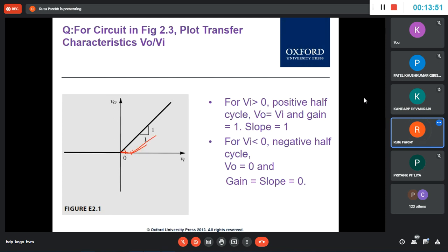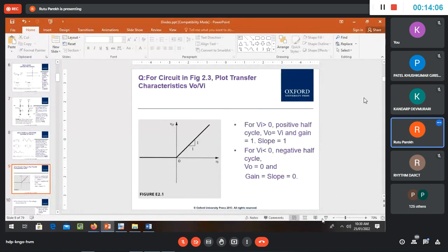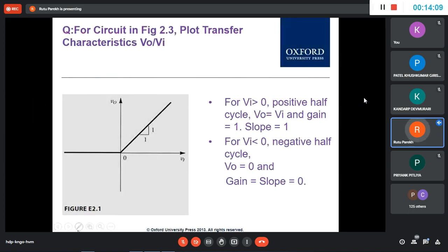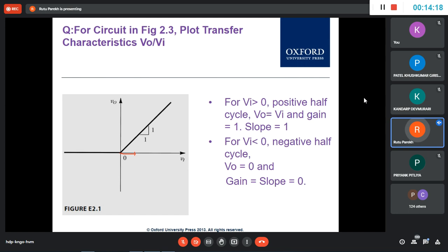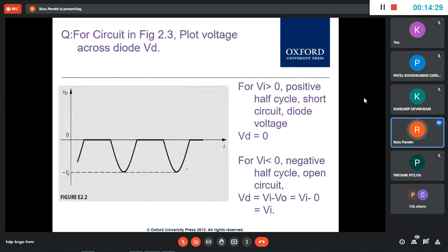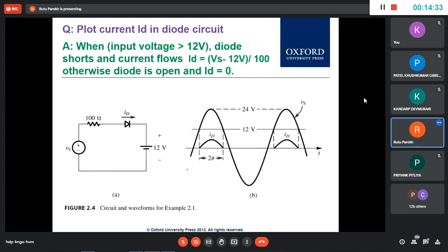So this is a straight line like this. Sorry, let me discard that. Okay, so whatever is the drop, if 0.7 is the drop, you will have a horizontal line up to that, and then in parallel you will have this line. So this is a straight line. If it is 0.7 volt, this is 0, so it starts conducting there. Is that much clear to you?